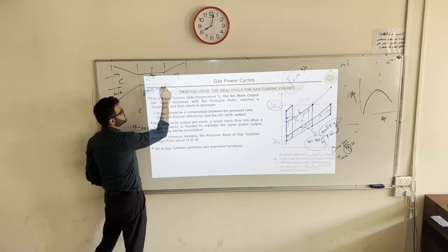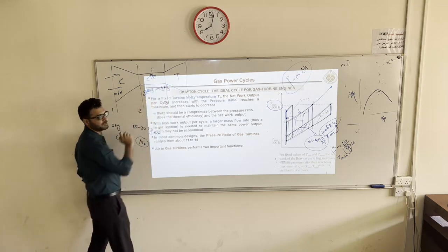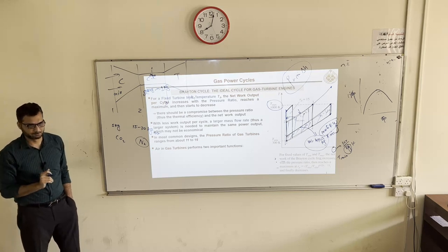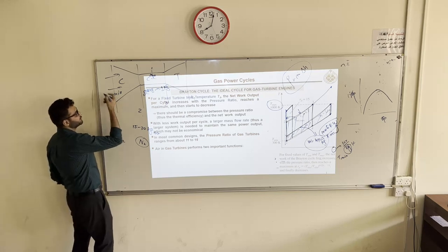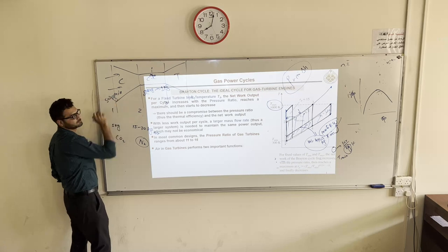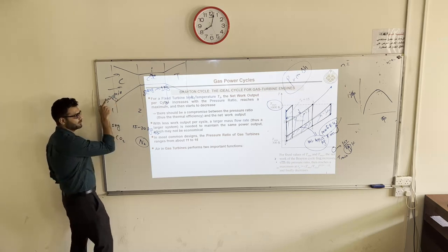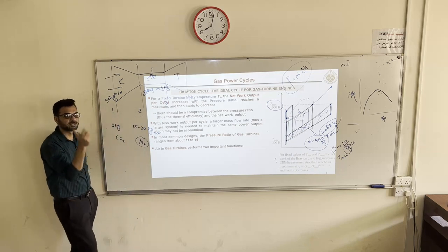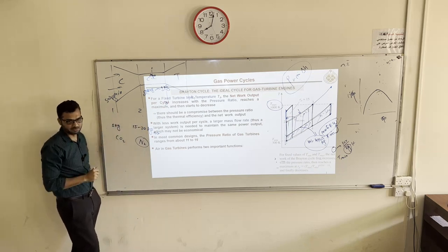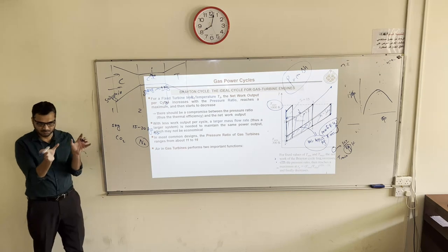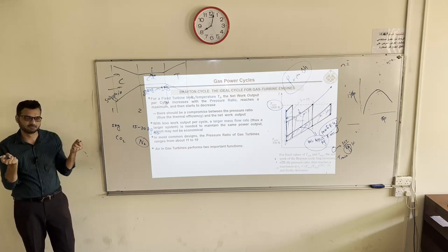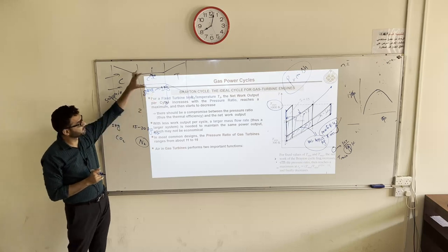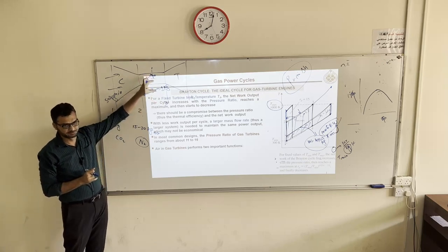So to burn this 1 kilogram of fuel, you need 20 kilograms of air, minimum, for example. But you will supply here 50 kilograms. So what will happen? 20 kilograms will react with fuel to burn. What is the purpose of the remaining 30? Some of the heat will be absorbed by this air, which is not taking part in the combustion, but is still present there.